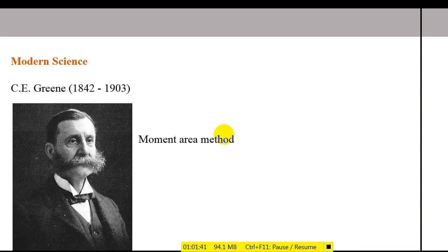So you might be thinking, why are we talking so much about beams? If you look at a structure, whether it is a beam, a bridge or a building, you can see beams are there. In every house, every building, beam and column are the main load transferring mechanism. The slab is resting on the beam, so beams are very crucial. Then columns are even more crucial than beams. If you don't have strong columns, there's no point in having strong beams. So you need to have strong columns.